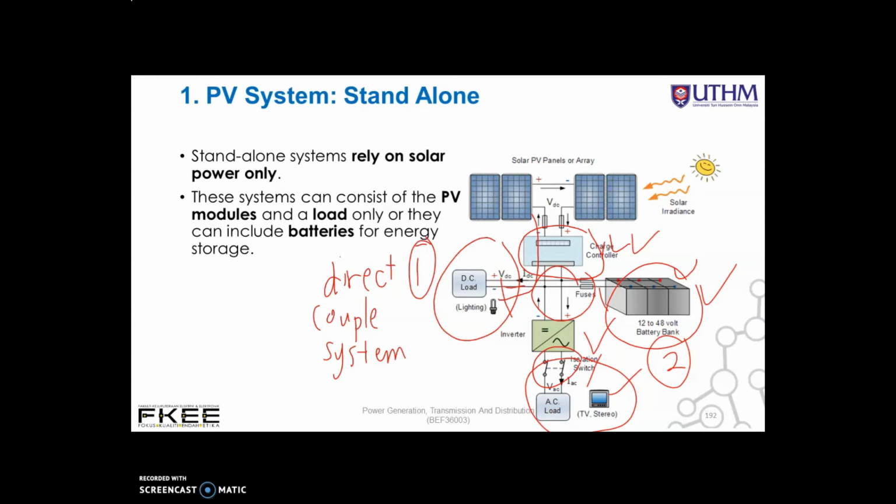And then the inverter. The inverter can be another optional unit in a standalone system. Basically, inverters are used to convert the direct current, which is DC power from the solar array and batteries, into alternating current AC electricity at either 120 VAC or 230 VAC for use in the home to power AC based appliances such as TVs, washing machines, freezers, and etc.